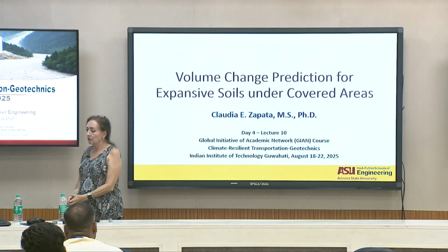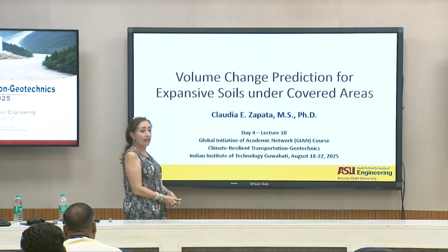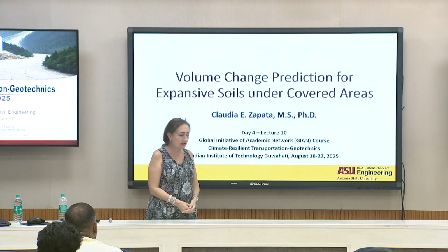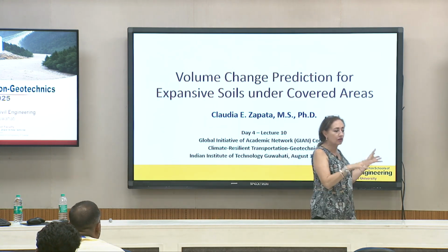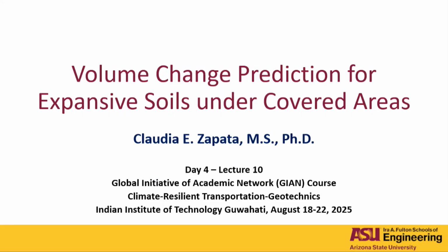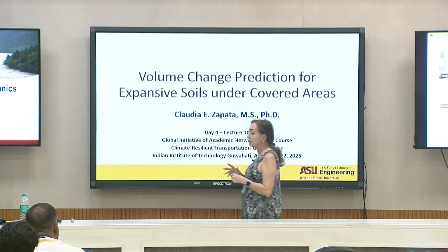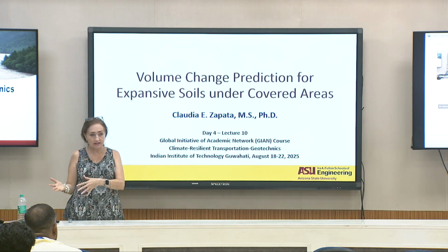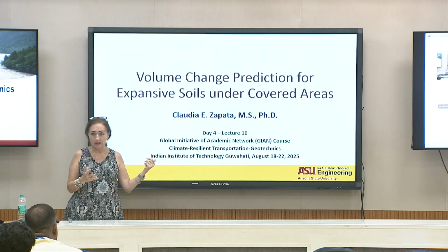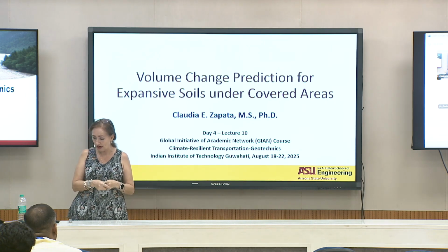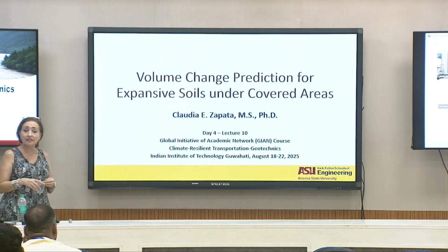Well, we decided that pavement engineering designers don't want to run finite element analysis and use the constitutive surface in here, where we can go up and down, back and forth in time and space. Then we could run some closed form solution for them, based on mechanistic principles, based on the two stress state values, right? The net normal stress and the suction values. And mostly on the suction values, because this is actually what will change.